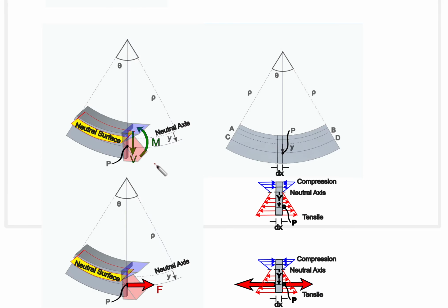First, we have to remember that in a beam we consider and generate the shear and bending moment diagrams for different x coordinates along the beam. And there is a neutral surface and a neutral axis that remains at the original length. At the same time, the bending moment generates tensile stress in one part and compression stress in the other, one below and the other above the neutral axis.